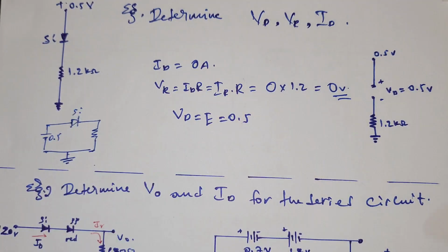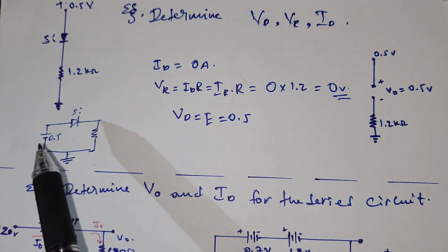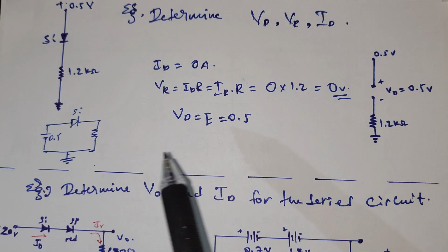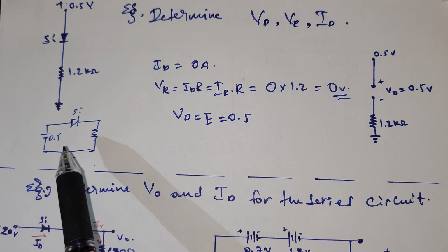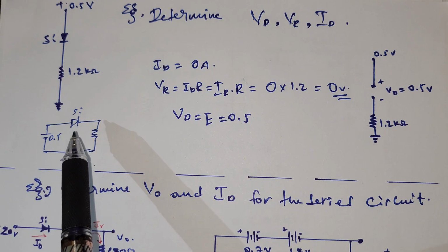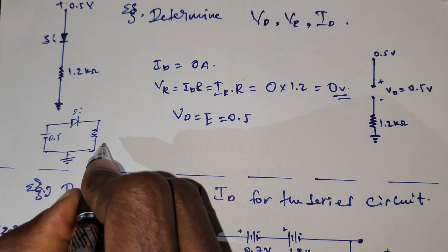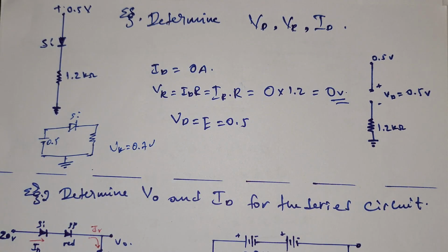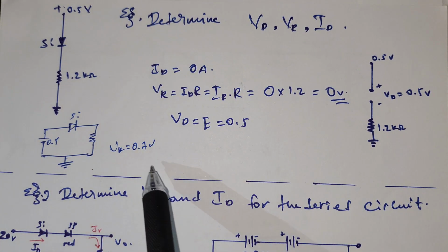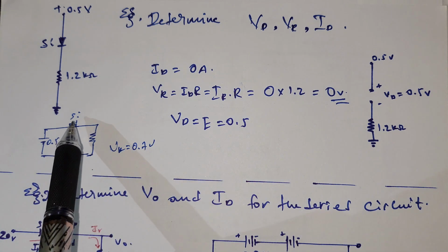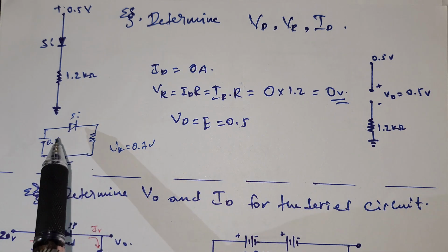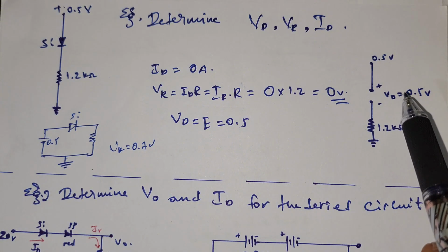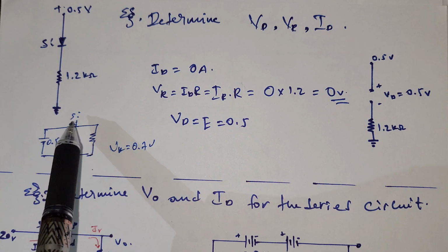This is silicon. So in order for the silicon diode to begin to pass a current through it, it needs 0.7 volt. Its terminal voltage Vk, Vk for silicon is 0.7 volt. So until 0.7 volt is delivered to this silicon diode, it would stay open circuit. So this is an open circuit.